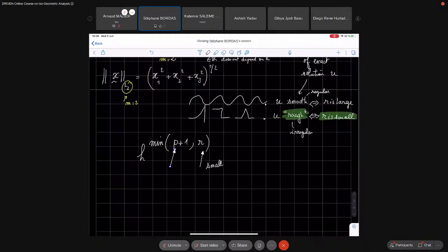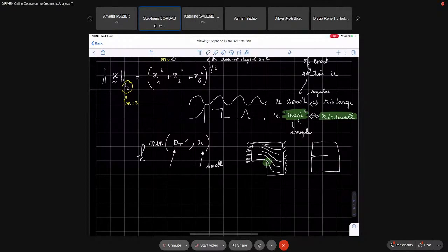Typically, if your solution doesn't work out, let's say you solve a problem, it could be an L-shaped problem, and you apply some boundary conditions on that, and then you will get some streamlines. The solution will look the way it looks, and you will have some large gradients at the corner. The same thing happens if you look at the crack problem, which is the limit case of this, when the angle is actually 0. If you pull on this, the streamlines have to go around, so they will be all compressed around the crack, and you will have high gradients here. So you have, in fact, a singular solution usually at the crack tip.